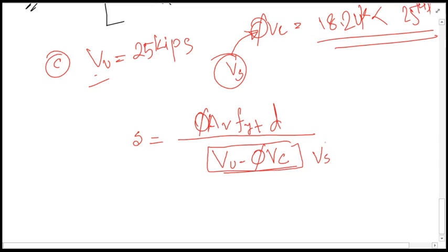The required amount of load that will be carried by the steel shear reinforcement is actually this one. That is, if you subtract the concrete capacity from the Vu, you will obtain the shear force governed by the shear reinforcement, Vs. So this is the spacing.